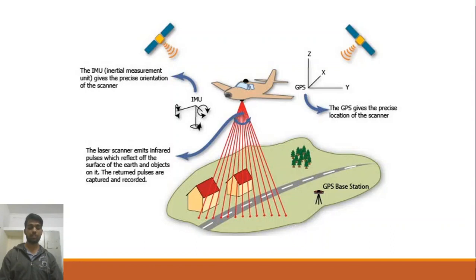to its source. The actual calculation for measuring how far a returning light photon has traveled to and from an object is calculated by multiplying the speed of light and the time of flight, and the result is divided by 2. Accurate distances are then calculated to the points on the ground and elevations can be determined along with the ground surface, buildings, roads and vegetation can be recorded. These elevations are combined with digital aerial photography to produce a digital elevation model of the Earth.